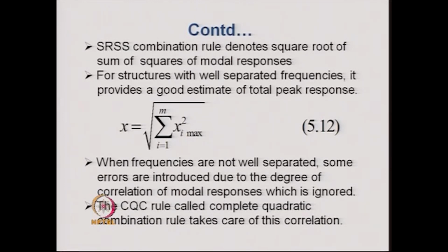Now, the effect of the correlation between the two responses in two modes of vibration can be taken care of by modifying equation 5.12, and the rule that we use for that is called the CQC rule, or complete quadratic combination rule.